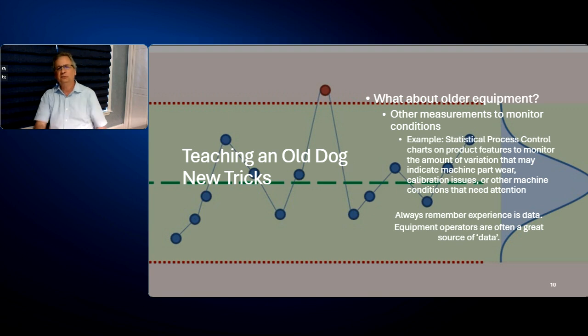What we did is we set up, I think it was about 4 control charts. The frequency was at least maybe 3 times a day: in the morning, in the afternoon, and I think there was one in the middle. They would take their data points, their measurements, and put them on the chart. We had control limits on the chart, and if it exceeded the control limit, they knew to call the service provider to come in.